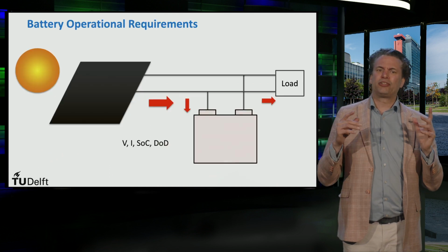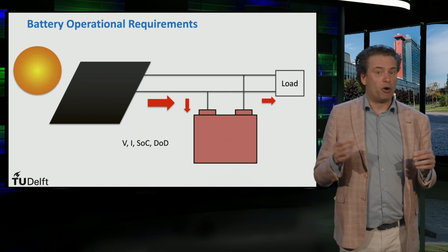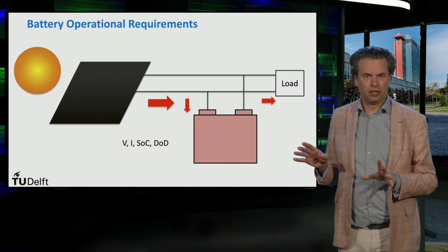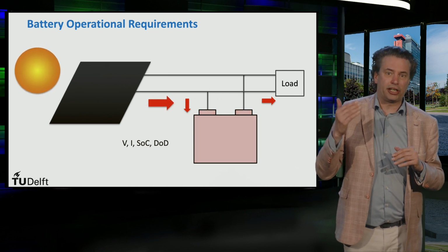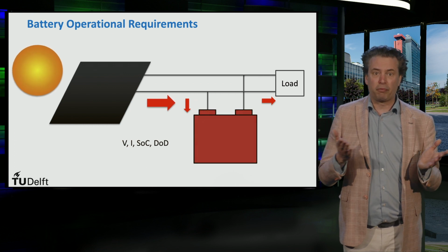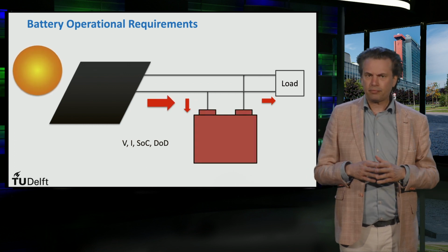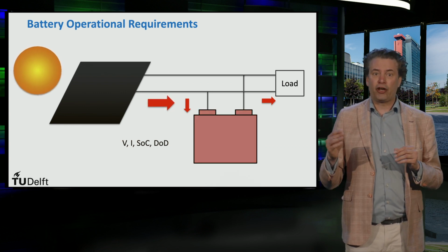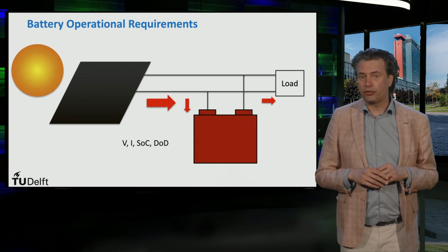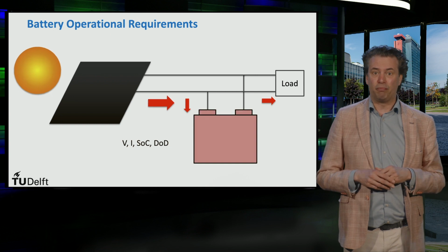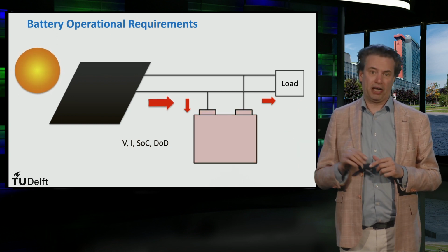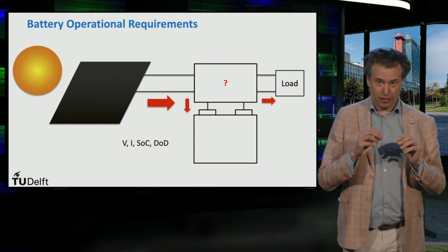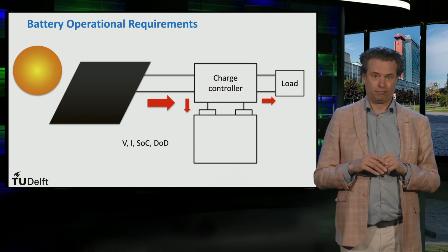To answer that, let's consider a simple PV system where the PV module is connected directly to the battery and no charge controller is present. When the sun intensity is constantly changing throughout the day, the current produced from the PV module will also vary. Because of this current fluctuation, the charging rate of the battery fluctuates and may, under some illumination condition, exceed the rated current of the battery, which would be harmful to the battery. To prevent this situation from happening, the device that is inserted in the PV system is the charge controller.